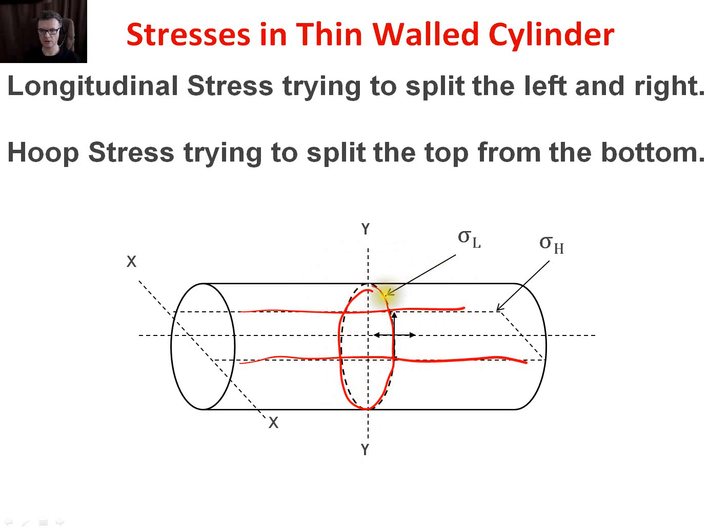Okay. So pulling it apart relates to stress being applied in the longitudinal direction, and making the cylinder come apart in this sort of direction relates to stress being applied along the circumference. Okay, so the naming convention looks a bit the wrong way around, because it looks like you're naming the stress in terms of the way the stress is cracking. It's perpendicular to the crack. You've got to think of the stress perpendicular to the crack. So the crack in this sense is going around here.